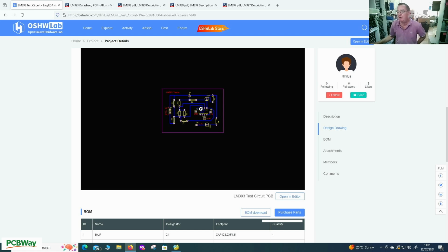First of all, because if you have a fault on one side of the chip, you wouldn't know there wasn't a fault on the other side. Okay, it's faulty, fair enough. But the original tester I had for op amps would actually test the two op amps in the package individually. You can see which one was failing. Okay, so I don't like that about it. Plus, we want to be able to make a quad comparator version of this, and we want a single comparator version. So I decided to have a look at the circuit and how this actually works.